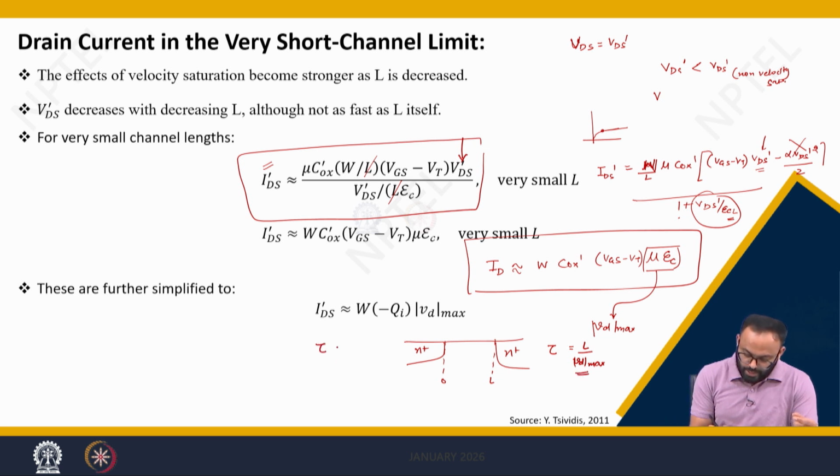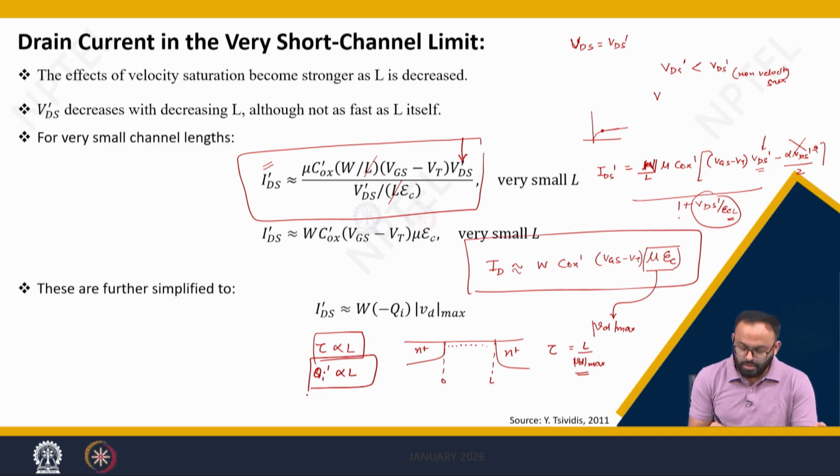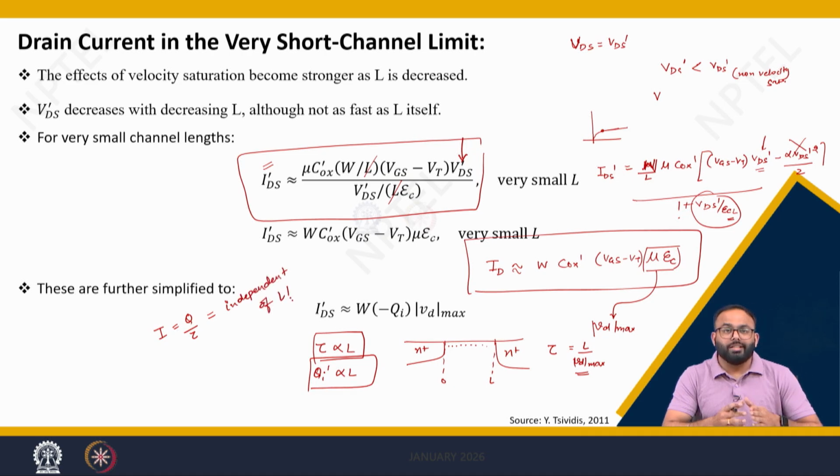So, the transit time of the carrier is directly proportional to L. And what about the charge? The inversion charge present here is also proportional to L. So, if you calculate the current under velocity saturation condition, it is nothing but Q divided by tau, and that will be independent of L. So, the current in the velocity saturation region will be independent of L.